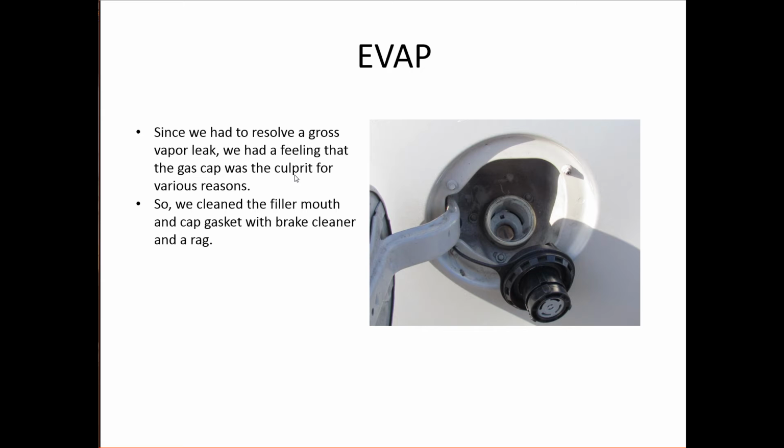Well, generally, the low-hanging fruit of a gross vapor leak is your gas cap. If you don't close that down securely, some of them click, some of them lock in place, or the gasket in there doesn't sit quite right on that filler lip, it can cause the EVAP system to trigger this error.